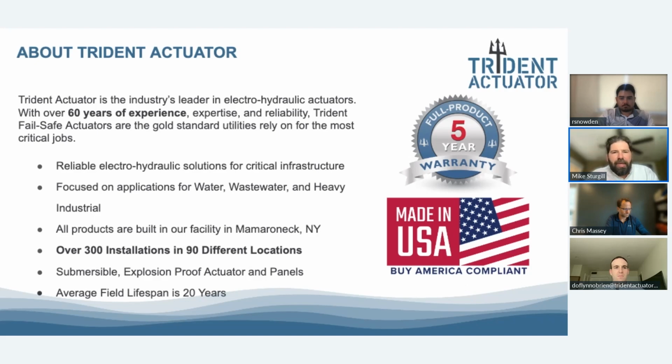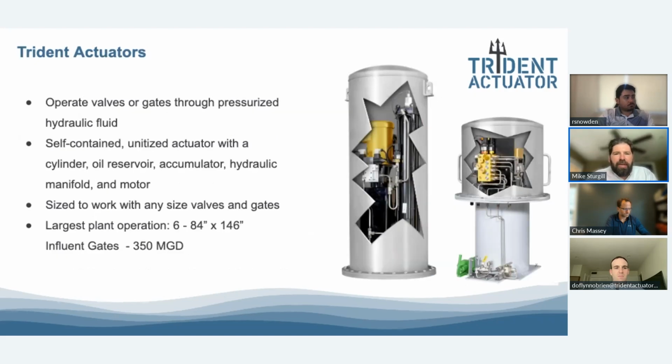So our actuators operate valves or gates, no matter what size, through pressurized hydraulic fluid. Our actuators are self-contained unitized actuators. We have a cylinder, an oil reservoir. If it's a fail-safe, which I'll talk more about, we'll have an accumulator and a hydraulic manifold.